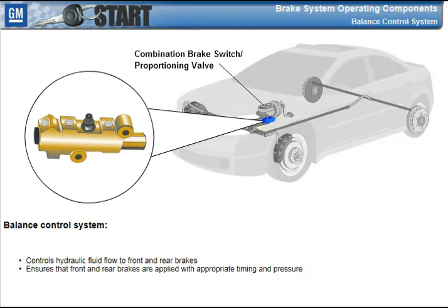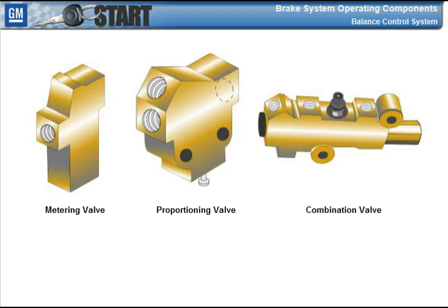The balance control system controls the flow of hydraulic fluid to the front and the rear brakes. It ensures that the front and the rear brakes are applied with appropriate timing and pressure. Depending on the vehicle, a metering valve, proportioning valve, or combination valve may be used.